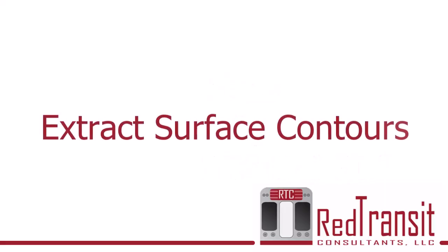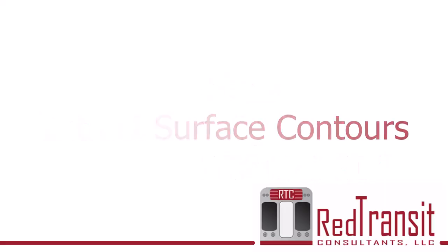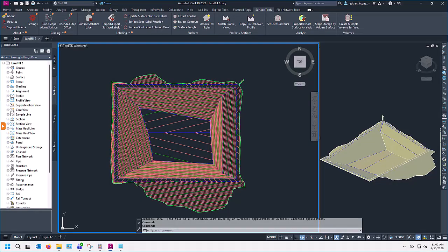In this video, we'll demonstrate extract surface contours. Oftentimes when I'm working with ponds or landfill liners, I have to extract contours, and those contours could be used for a number of things. In my landfill liners, I often will extract a contour to act as partial boundary for another surface that I'm grading that needs to be at a specific elevation. In ponds, I'm often extracting a contour at a specific water elevation to show in my plans.